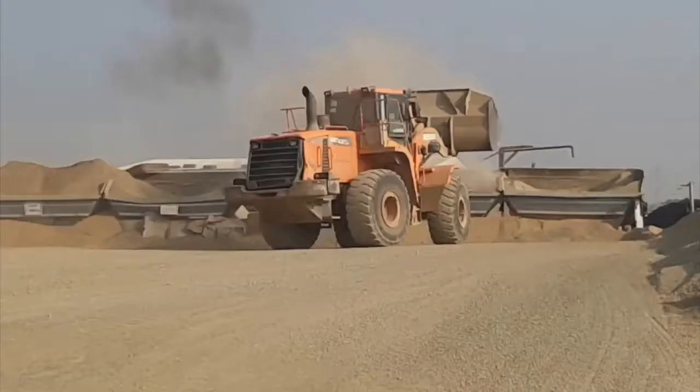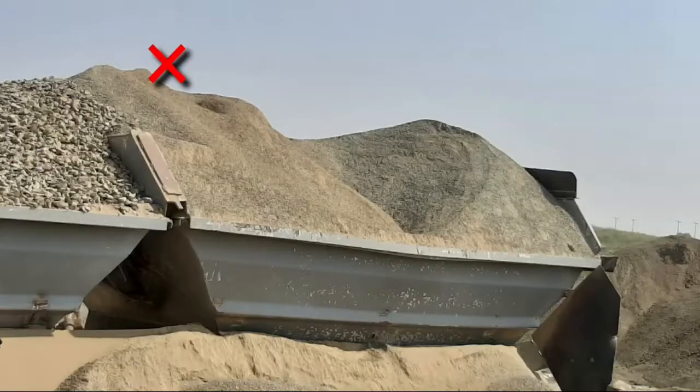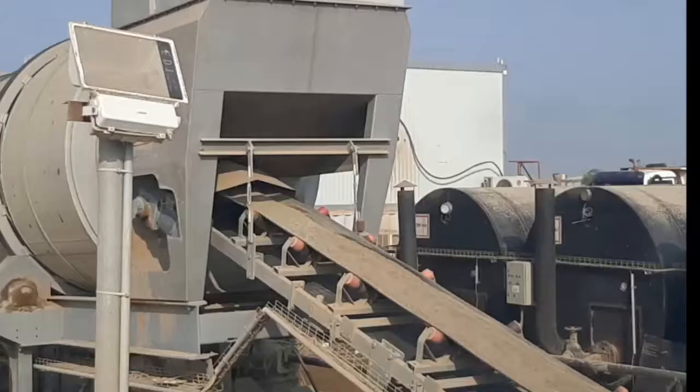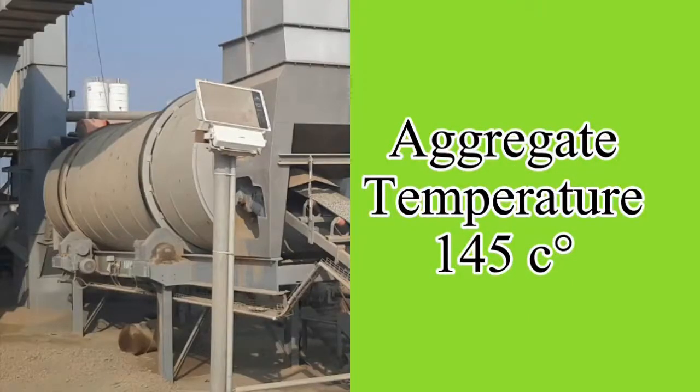Move the material one by one in cold bins. There should be separate cold bins for all aggregates. Avoid mixing one bin material to other bin material. Ensure that all cold bins discharge gate is working and aggregate from each bin is transferred to belt properly. Move the aggregate from cold bins to dryer.